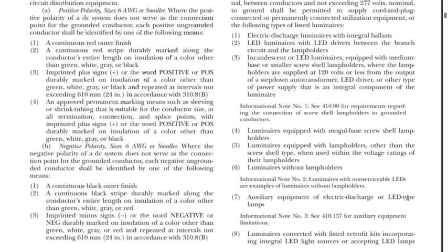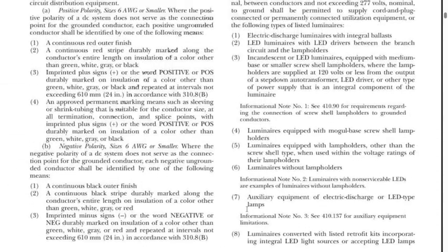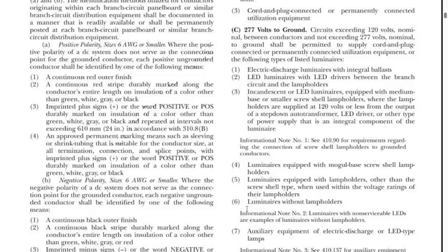is lights. It is all lights, all the way down. 1, 2, 3, 4, 5, 6, 7, 8, 9. No, there's no 9. Lights. So in other words, all of the lighting systems can be a maximum voltage of 277 to ground, meaning hot to ground. Now, they could have said hot to neutral here. It doesn't matter. They've just chosen to express how we would check the voltage in the system, hot to ground.